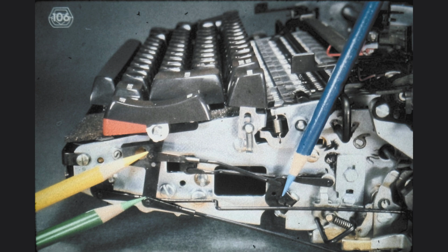The détented positions of the switch also hold the positions of the on-off key lever. Whenever we change the adjustment of the link connecting the key stem to the switch, we must also correct the length of the keyboard lockout bail link at the yellow pencil.